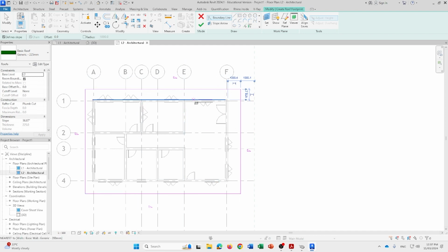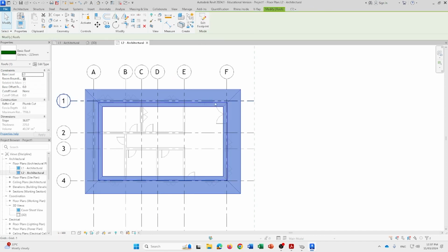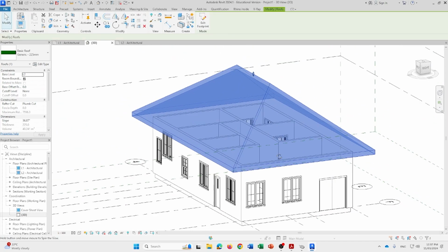Okay, before we confirm it, I'll just explain how the roof slopes and the different angles work. To deactivate the tool, press escape twice on your keyboard. Now you will see these slope icons. If we click on the outline, these define the slopes of the roof. Right now, every outline has a given slope. Don't click the big tick next, I'll just show this as an example. If you have all 4 sides with a slope, this will give you a gabled roof.